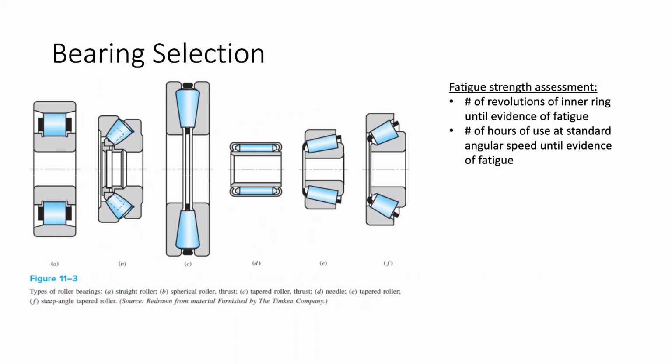That's partially because they can't hit those tolerances well enough when they machine these elements, but also because if I'm inserting a shaft and doing something like a press fit where it deforms the housing, I don't want to immediately load my bearing elements with that press fit, right? So you have this slight mismatch in the spacing of these bearings. And what you're actually supposed to do is something called preload. Preload means that you apply a small amount of load to the bearing to begin with, and that gets rid of the free play and compresses the bearing slightly.